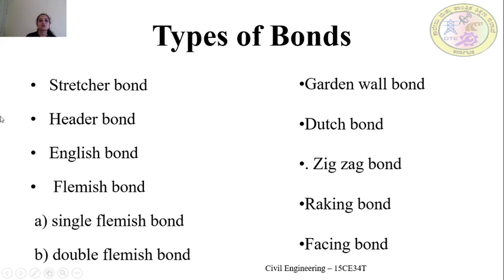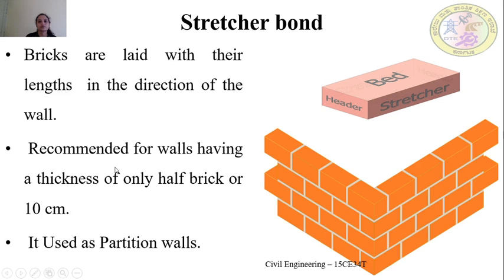In this particular session, we'll concentrate on stretcher bond, header bond, English bond, and Flemish bond. So what is stretcher bond? In the initial slides we discussed what a stretcher is. Stretcher bond means the bricks are laid with their length in the direction of the wall.